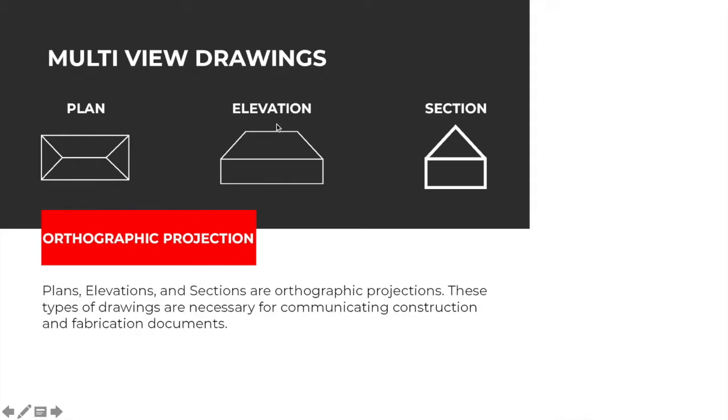If we were to cut a simple section through that elevation, we might start to see the thicknesses represented of the joists as well as rafters and the walls, and we would poché those portions that are solid to communicate to the viewer that we are in fact cutting through portions of this that are solid, and understanding the mass-void relationship. Back to our understanding of positive and negative space and how positive and negative space represents mass and void, that carries through into the conventions of architectural drawing.